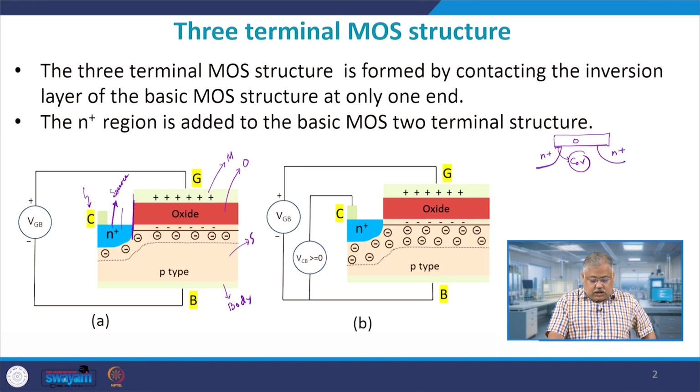With this knowledge, you can see that the inversion layer is already formed. You have these negative charges formed near the silicon dioxide interface, and there is a depletion layer here. But the interesting thing now is, if you concentrate on this particular part, this is nothing but an N plus P layer. There will always be a depletion layer within the N plus P layer, because it is a p-n junction diode, and the thickness of the depletion layer will be more towards the p side.